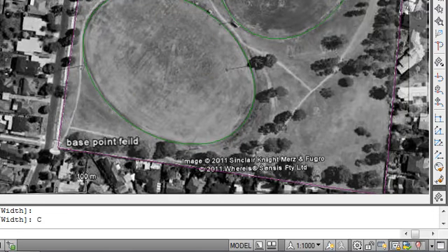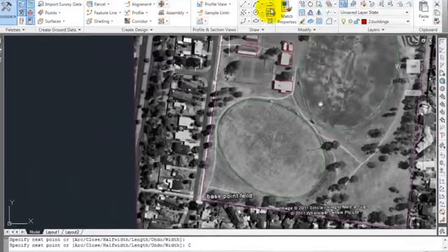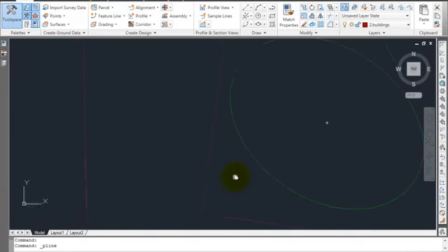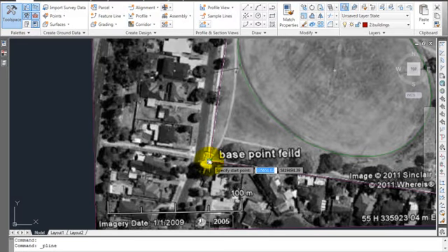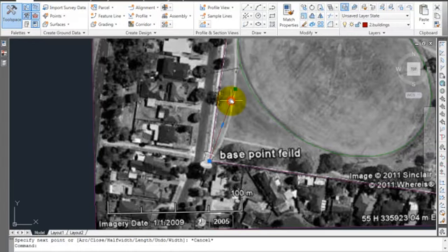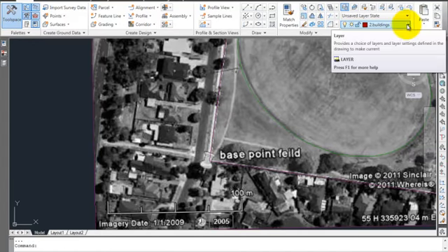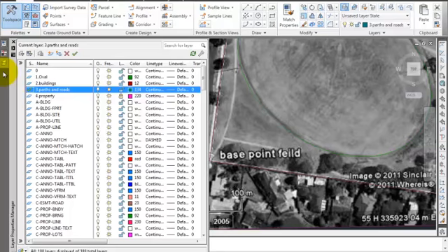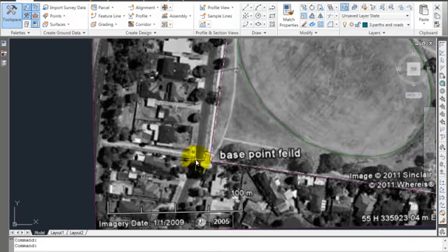You notice the paths are also straight and curved. Now one of the things I'm going to be using again is this poly tool, because it's actually got a few more functions than what you actually do realise. Now what I'm going to do is again put my base point in. I'm going to just basically go to points, and again I've actually used the wrong layer, so I'm just going to escape from that, delete too quick, and make sure that I do go to paths and roads. And again, this is a good reason why you should be labeling your layers.